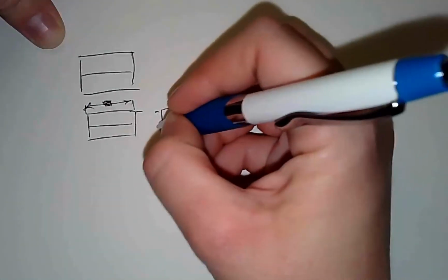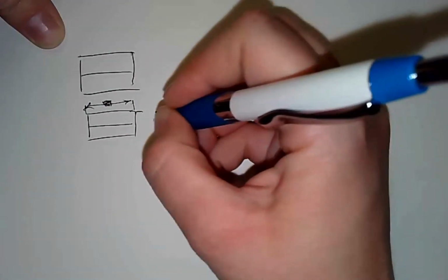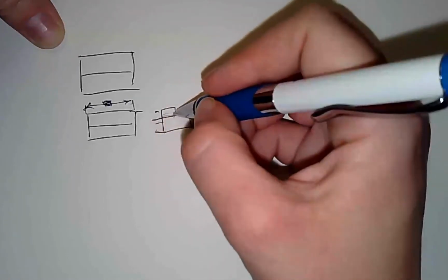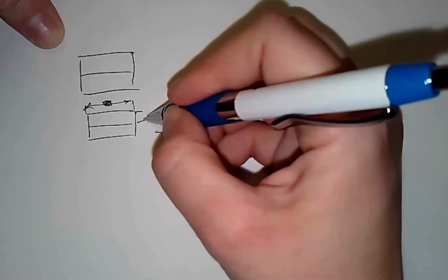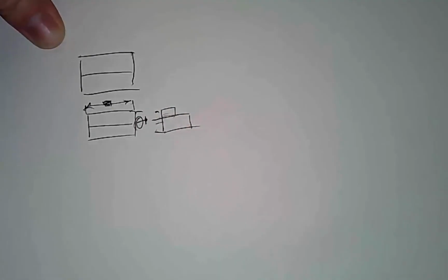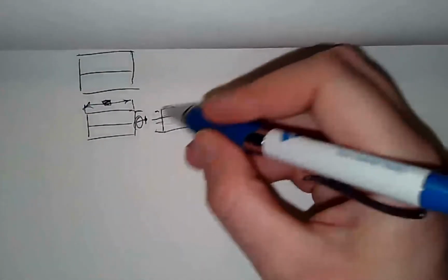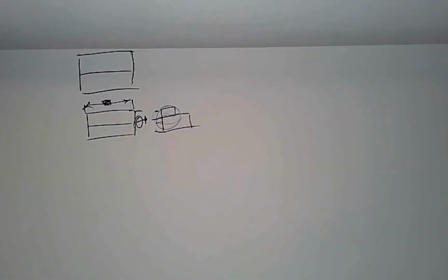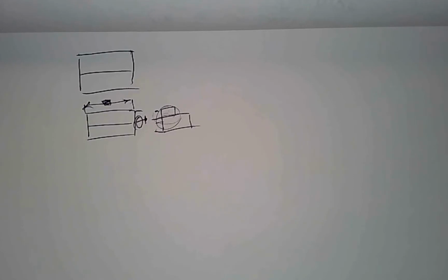And you want to do that in order to minimize this kind of situation, right? I'm not going to have to pull that dimension in that direction if I can pull it from over here instead. And then I don't have to overlap the actual object line using a dimension. So you want to provide sufficient dimensions, but don't add duplicates, right? So don't duplicate that information unless it helps make it clearer, okay?